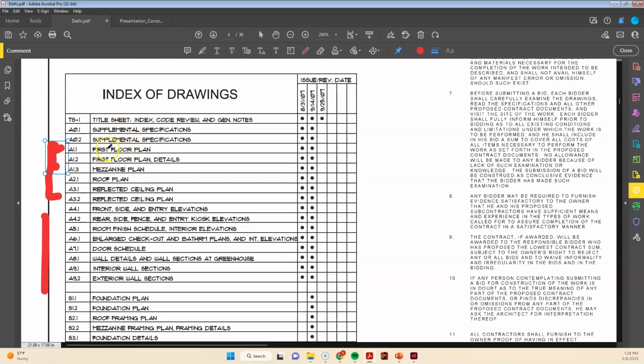So all these plans are maps for all these details that are going to come, followed by the floor plans, roof plan, and reflected ceiling plan, the RCPs as they're called. We have elevations that follow, and then schedules and interior elevations. As we proceed further, we get into more and more detail about this building. Then we have doors, and enlarged plans of bathrooms, very important to lay those out very carefully, especially for accessibility issues. Then we end with wall sections, which are really the most detailed.